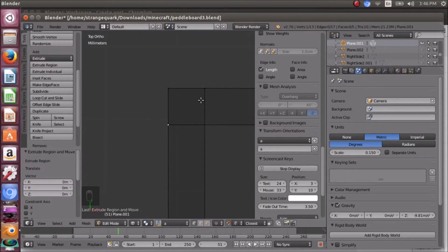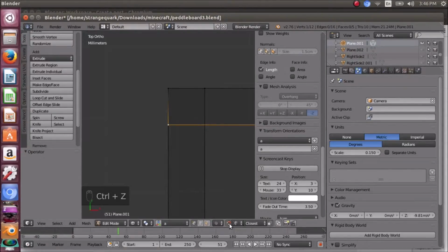We can use the snap function down here that I'm showing, snap during transform, and we can snap to the closest vertex. The nice thing is if you want to replicate a measure, you can do so using existing vertices. So we know that for the X length, this vertex right up here matches the length of the intersection between the two plywood walls, or it would be the interior vertex representing the intersection of the two walls.